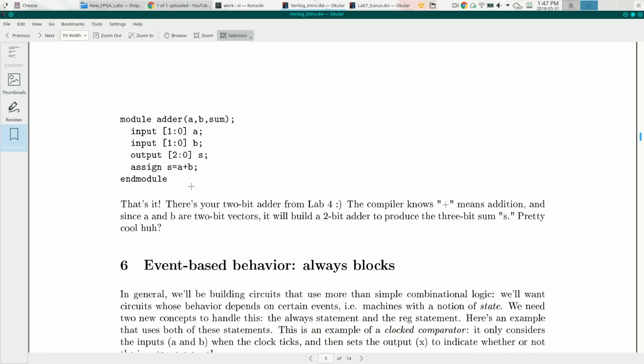So we're going to say, what do we want our system to do? When the clock ticks, what should it do? Well, if the state variable is currently 1 and the input is 12, then I want you to set the output equal to 3 and go to state 7. And we can basically write a Verilog statement that says that. And we do that for all the different situations that we might encounter. We compile it up and it'll build a state machine for us.